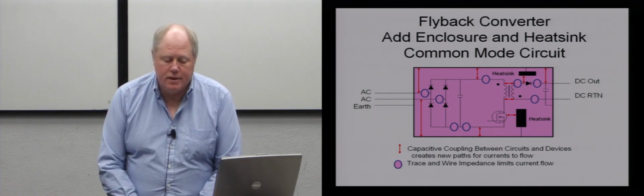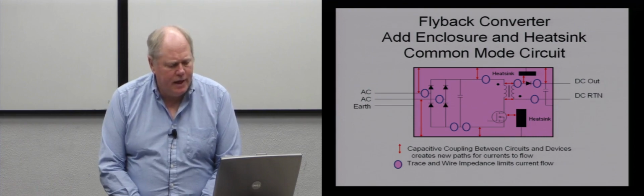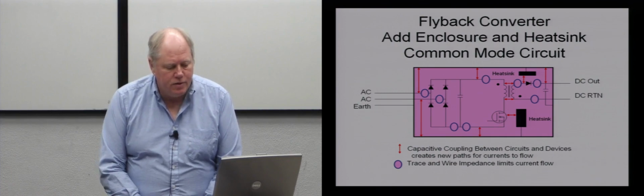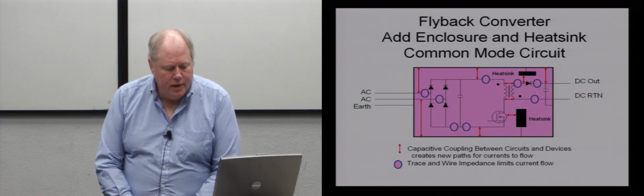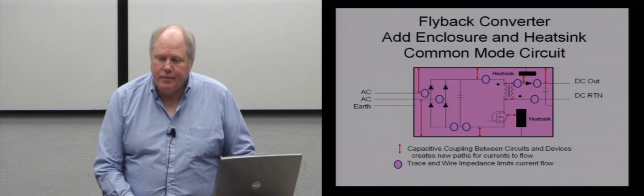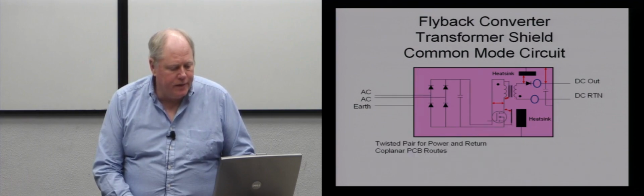It becomes a big antenna then. And then that kind of happens all over the place. You might have another heatsink on the diode. In your transformer, you've got windings next to each other, and you make a capacitor between the primary and secondary.